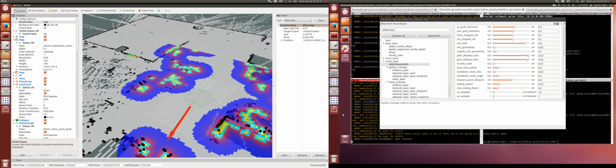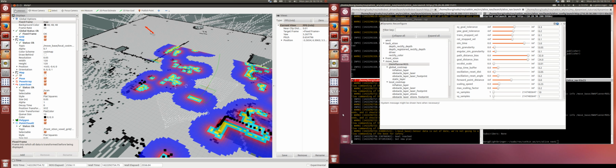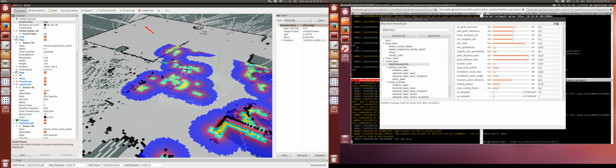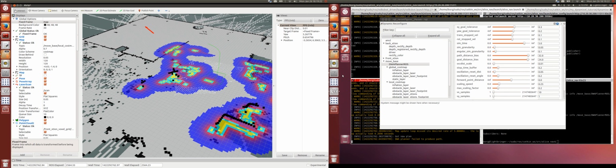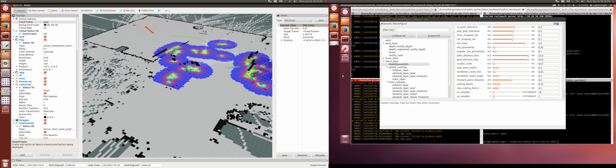And finally, the other thing that I found out was that on the ROS forum, on the DWA local planner, there is a penalizing of negative X. However, I don't see where it is used in the source code. I'm not sure whether it's actually being used or not, but I think if you enable the forward point distance, then the robot will not move forward as much as it should.